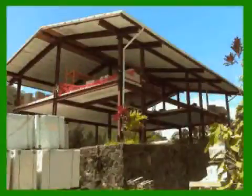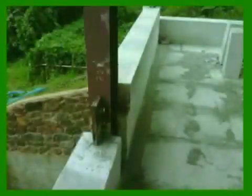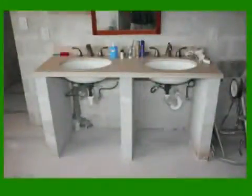Let's look at the 3-story residence in Hawaii, a 5,000 square foot house with a pool. Due to the extensive use of windows on the west side and having AAC floor panels on this project, and thus also being in seismic zone D, we used a moment frame structure.